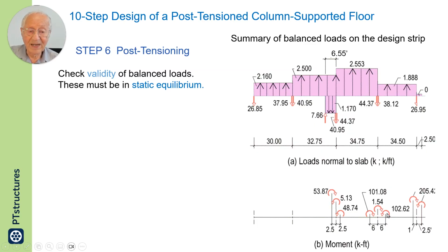Wherever there is a change in centroidal axis, there will be bending moment. So here I have shown the entire balance load, the entire forces that the tendon applies to the member, consisting of up and down and moments.